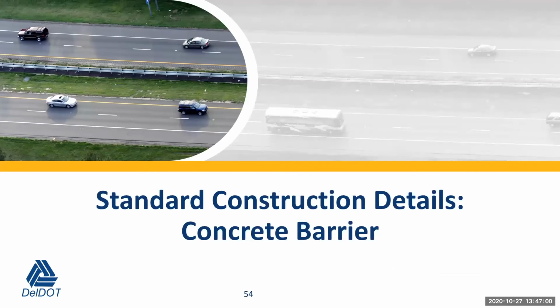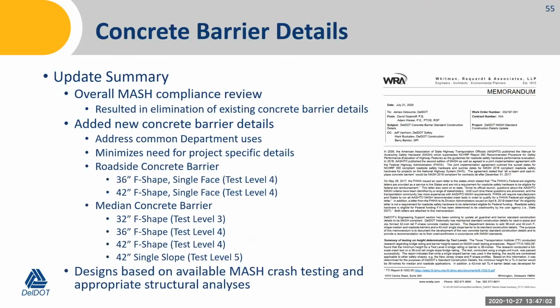All right, we'll touch on the concrete barrier details. So again, just an overall update. We did an overall MASH compliance review, which pretty much resulted in elimination of the existing concrete barrier details and replacing them with new details. For the new details, we addressed common department uses. The goal here is to try to minimize having to have project-specific concrete barrier details and have a standardized detail for our various situations.